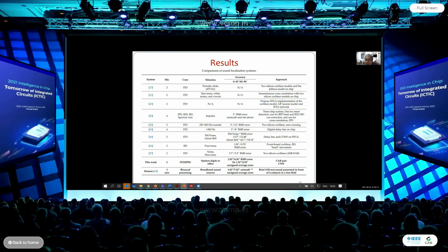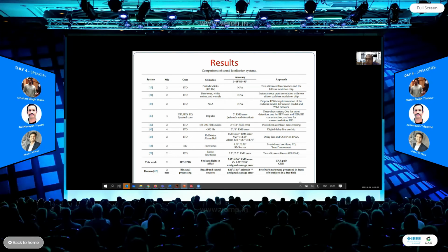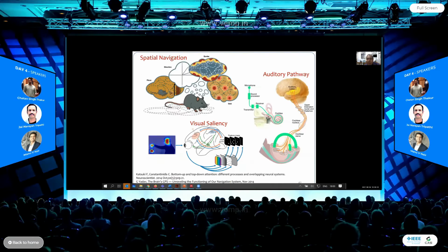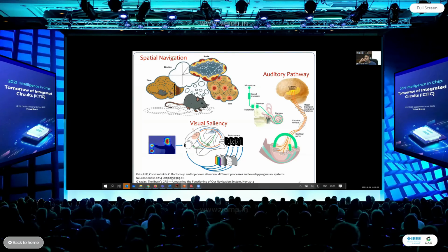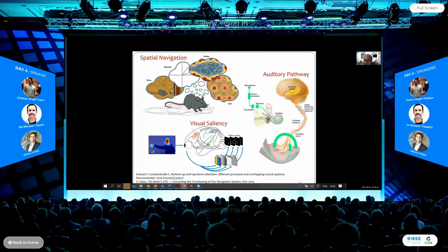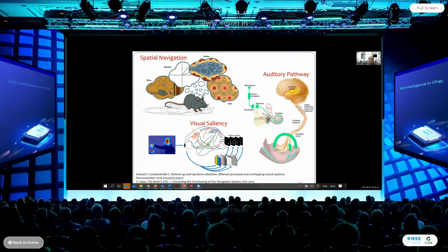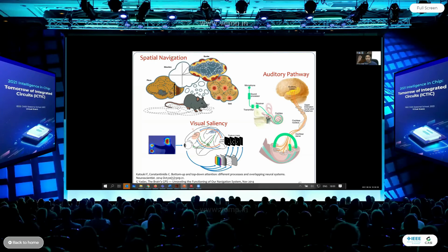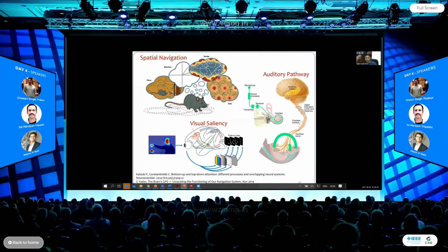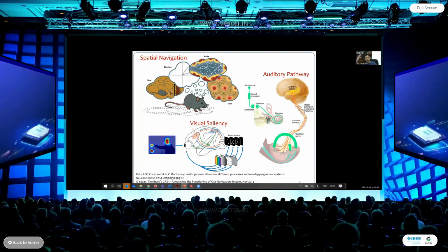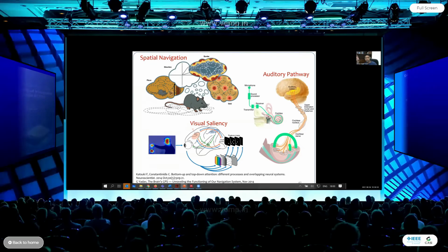There is one question. As far as hardware implementation is concerned, what about the area and power related aspects? I mean, specific to a particular application you're talking about? See, whenever you implement in this parallel architecture, you will always get benefits when you go either in the VLSI domain, either FPGA or analog or digital, because you get the parallelism, right? And that's how even the brain's architecture is based. So you'll always get better PPA metrics as compared to running on the CPU. This is the general answer.